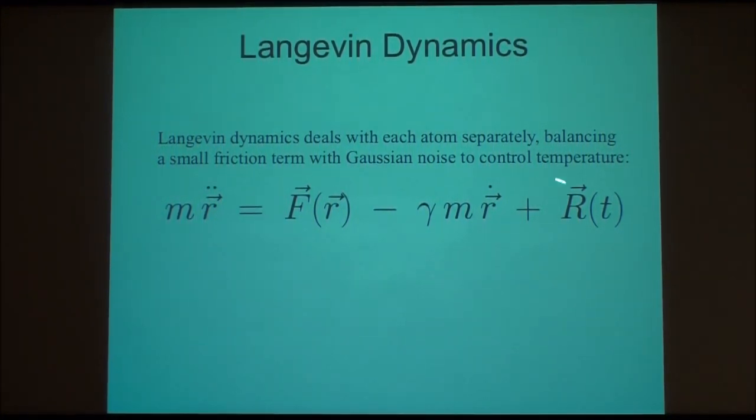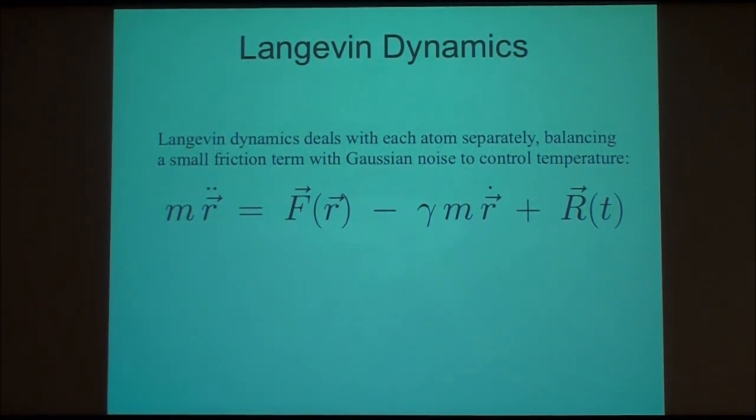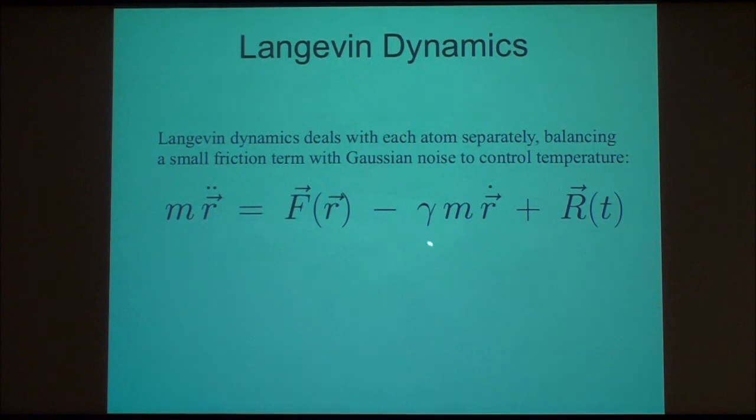These two terms usually come together. One of them essentially introduces the effect of friction of the system, of the environment. So this gamma is a parameter that you specify in your simulation configuration. The larger the gamma, the higher the friction would be in your system. You damp the motion of atoms much more strongly by increasing the gamma parameter. Since we are usually limited in the time scale that we can reach using these simulations, it's highly advisable to use as small as possible values for this coefficient.